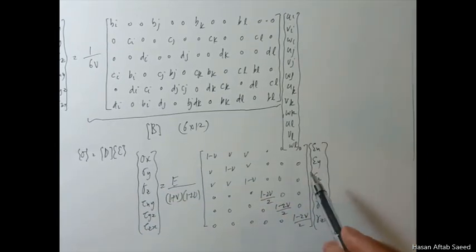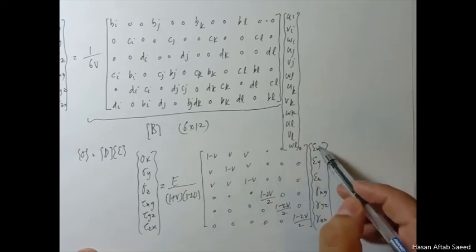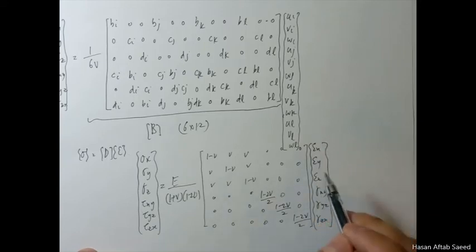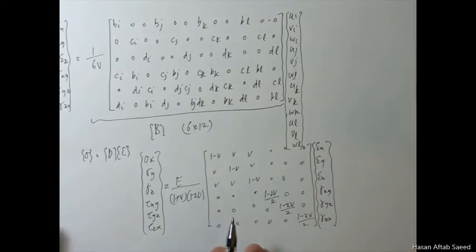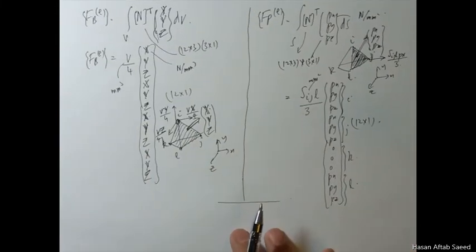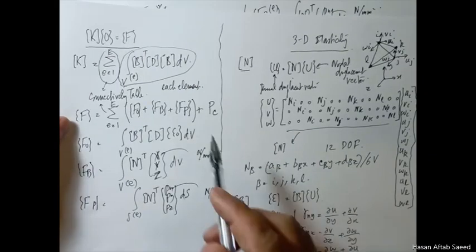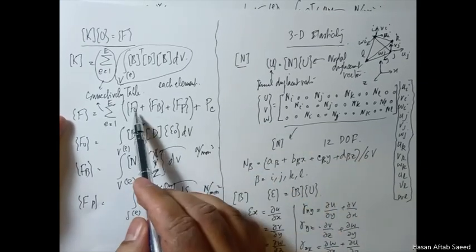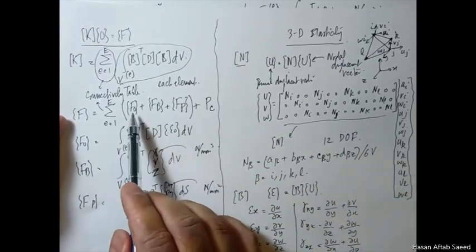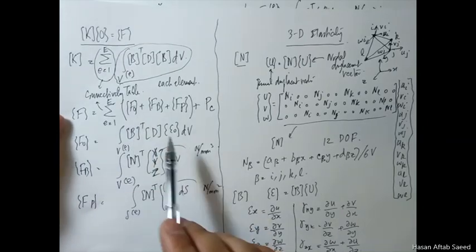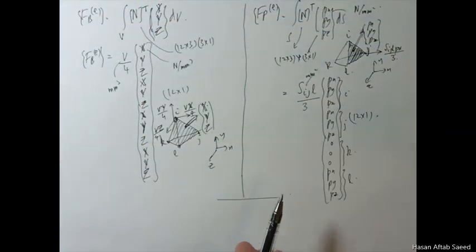Now if you use this expression to get this, which you do at the end of the problem, you must make sure that this is a vector of mechanical strains, not total strains, because recall, when we formulate the problem, we always apply this initial strain vector, which is a result of temperature changes. So the displacements you get as a result of FEM include total strains, including thermal strains as well as the mechanical strains.